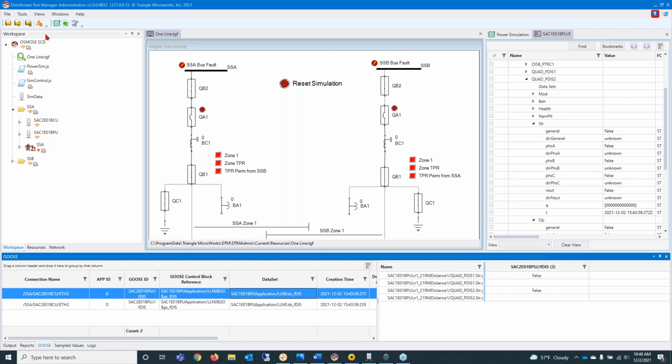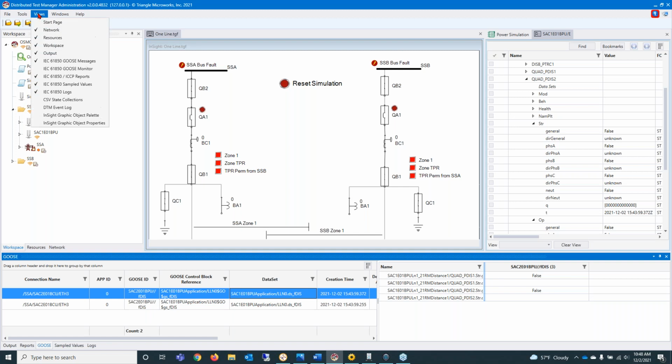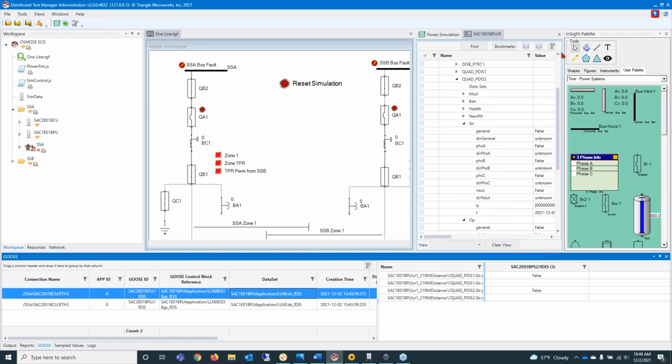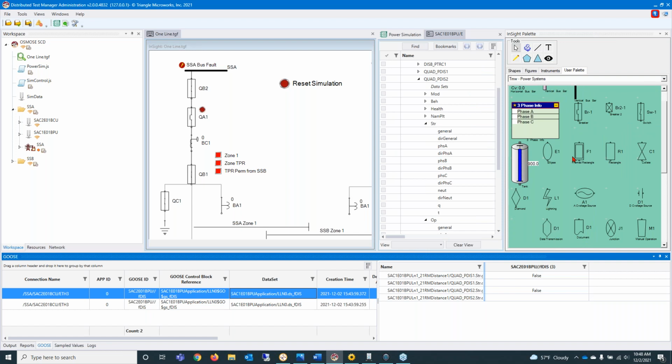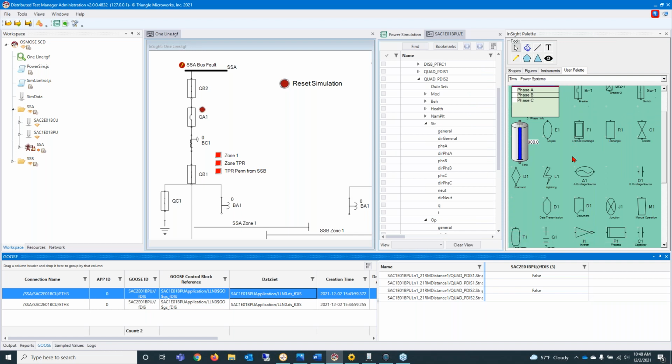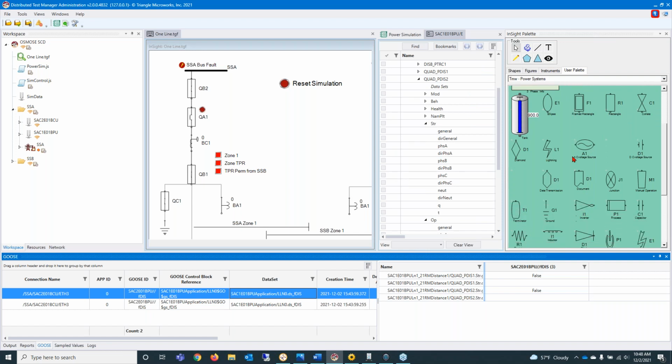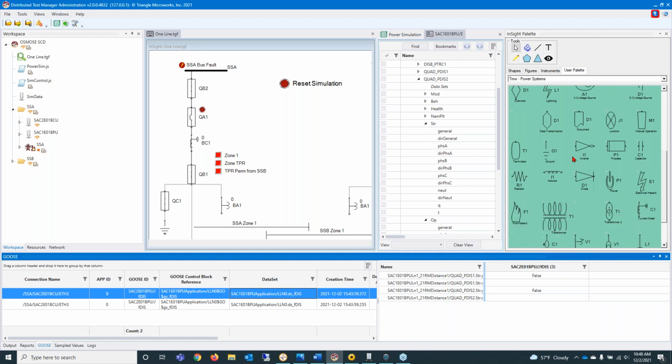Yeah, maybe to add on with 61850, we basically have the possibility as well to describe and include network switches in the communication and describe the connectivity of that in 61850. That's basically using the extensions from part 90-4, where we have a model of switches as well. So this supports the possibility to describe a network diagram in detail.